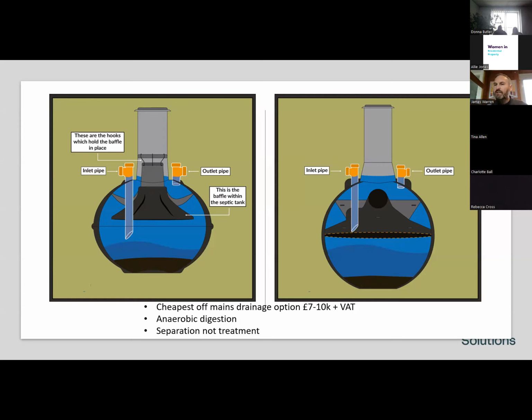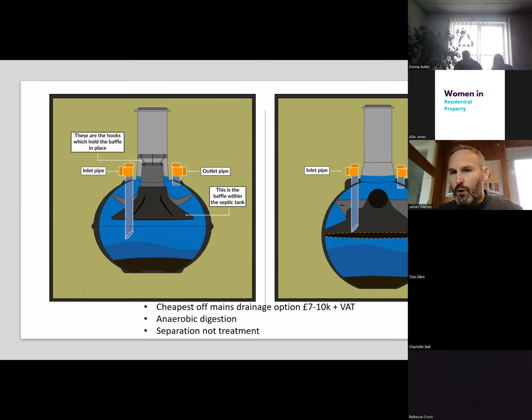And if I may, if I draw your attention to that darker circle at the middle of the baffle cone, that's a baffle ball. It's about the size of a football. It's effectively polystyrene and resin coated. The job is effectively to form a plug. When that tank is empty, that baffle ball will sit on the base of the tank. As the tank fills, when we use the toilets and the bath and dishwasher, etc., the ball will go with the height of the liquid level.